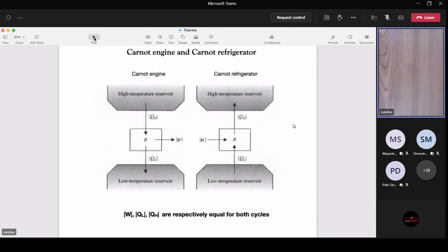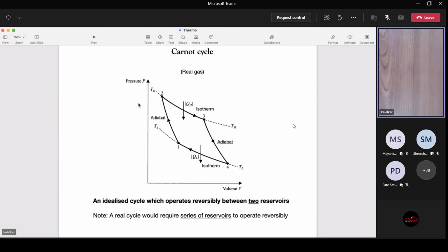and we will use generally the Carnot cycle for understanding a lot of thermodynamics. So it's really useful, the Carnot cycle, and it's useful because, as I said, the essential features of heat engines and fridges are encapsulated in a single diagram. You don't have to worry about the details of one engine versus another engine. We will do that, but that's hiding the basic facts within. So this Carnot cycle in a way exposes the essence of a heat engine or a fridge. That's why we study the Carnot cycle.